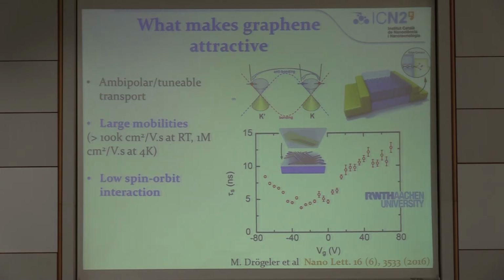Okay, so this is now completely incredible, and we can reach very high mobility in CVD graphene, which is an upscalable material. So that's key for technology. At the same time, the spin lifetimes that we reach today, which are, let's say, 10 nanoseconds, are good enough to demonstrate that we can engineer functional active spin devices. So we can move on this search for spin logic technologies.